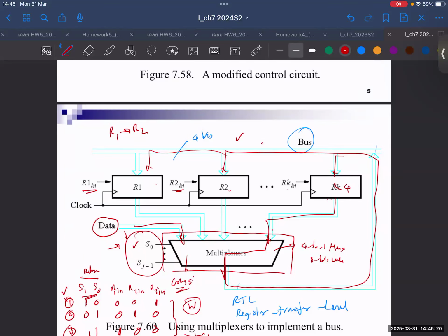And when it optimizes, you can tell the tool to compress or use the minimal resources possible, or let's say, I don't care about the resources, but I want it to be as fast as possible. You can tell that too in the tools. And of course, usually it will blow up your hardware. Instead of just one, it may be 10 times the hardware, but it's going to be 10 times faster too. Understand? So it's a trade-off between what we call the area and the speed. So if you understand tools, then you can do that too. That's why if you want to be a good designer at this level, you need to understand these three things. Okay. And then you'll be good.